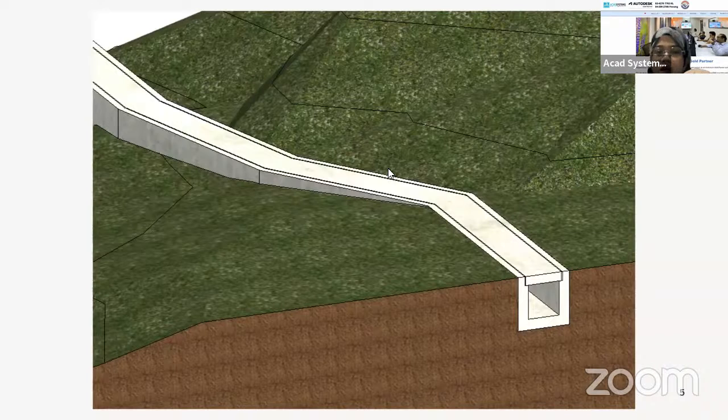Thank you. Okay, so we're just going to create more or less this kind of trench placement on the topo solid. This trench placement, you either can place on the topo solid, or on the slab, or on the floor. Or if you don't want to place it on any model, you just want to make it a free placement of the trench drain, that also can.